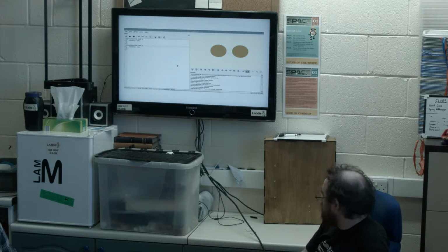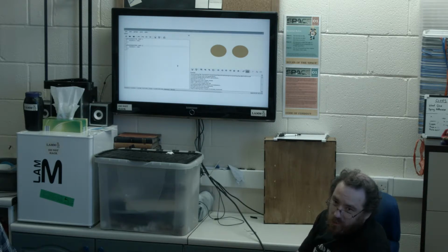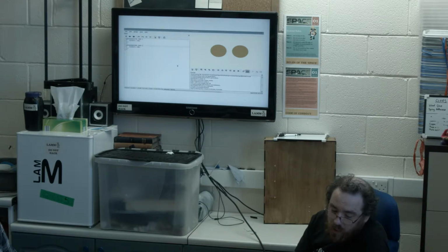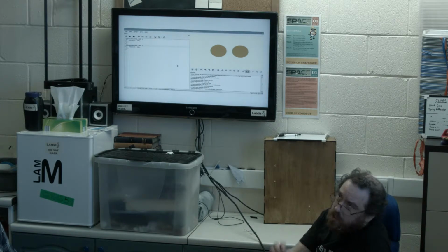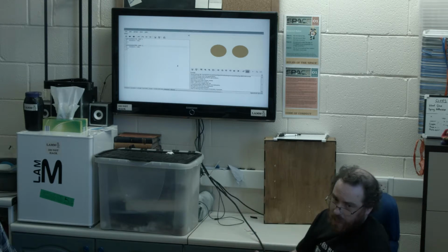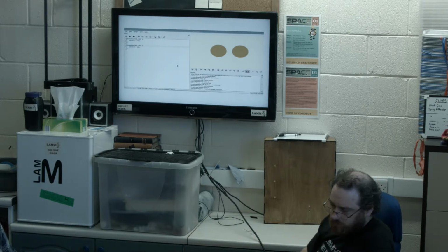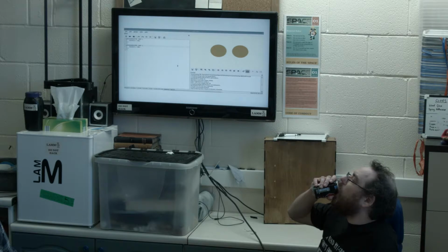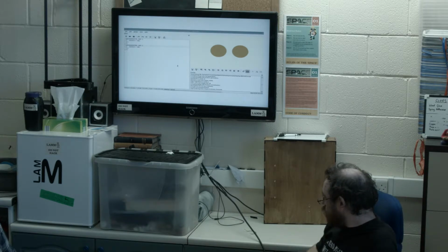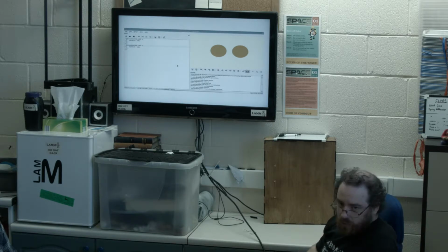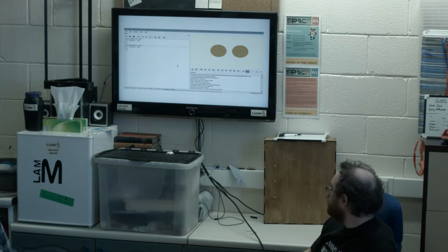So yeah, you can put 2 circles next to each other. So you've got the translate option, which allows you to position it. And obviously we're only working in 2D space at the moment, so we're only doing X and Y. One of the things that I really like about OpenSCAD is that you can always see the axis, and you can even have a ruler out of it if you turn on the two buttons to the right of the one already depressed.